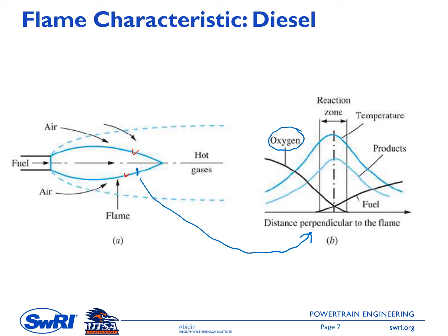Inside the fuel spray, we have a higher fuel concentration, and then there will be a reaction process inside the flame front because we have a composition of oxygen and fuel within the range of the stoichiometric composition.